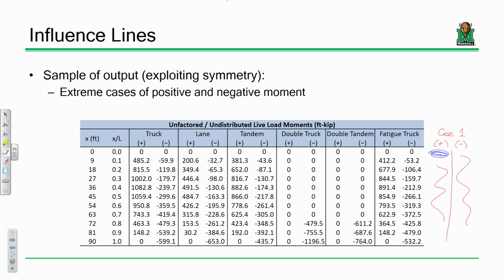Let me say this. You are bringing up an interesting point. All this stuff that we're talking about here is only concerning placement in this direction. We haven't yet talked about placement in this direction. In order to assess that, what we have to do is utilize what are called live load distribution factors. And live load distribution factor equations change depending upon if you're looking at a steel I-beam bridge or a concrete T-beam bridge or a steel box girder bridge or a concrete or whatever. So does this change? No. But does your transverse distribution change? Yes.